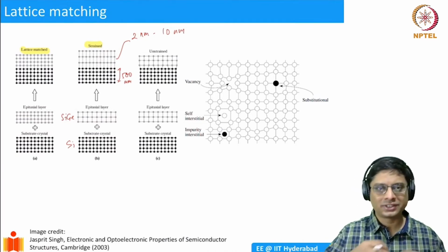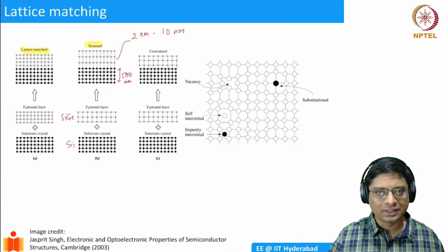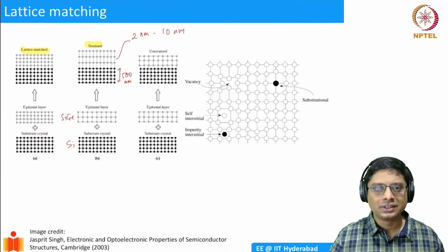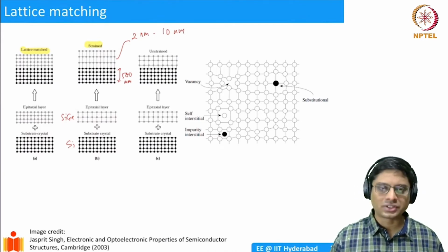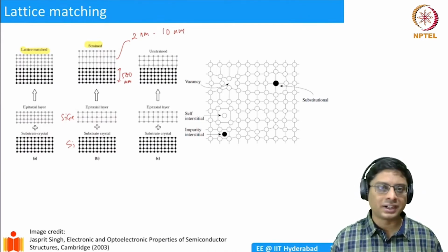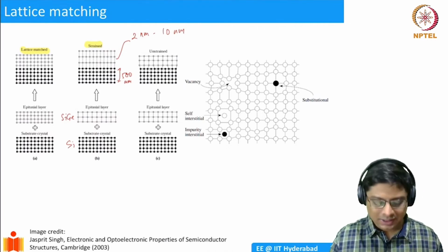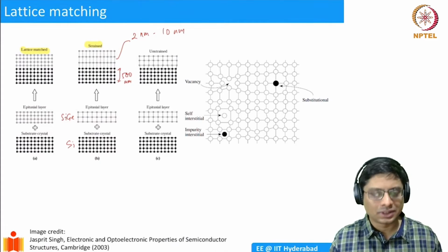For example, in the NMOS devices, there was tensile strain applied, and then in the PMOS devices, there is compressive strain. If you do that, the mobility was improved, and that's how they managed to improve the drive currents in the 65 and 90 nanometer technologies. Okay, something similar happens, and you get a different material.